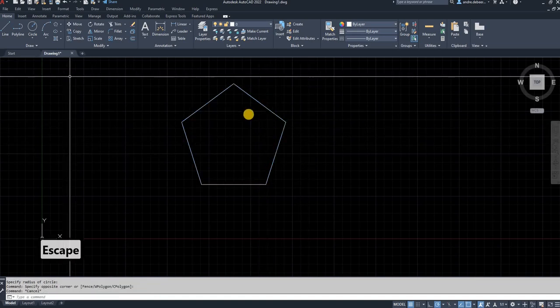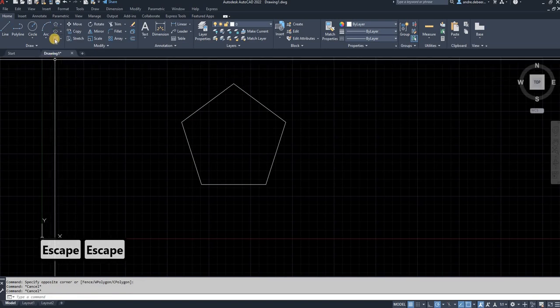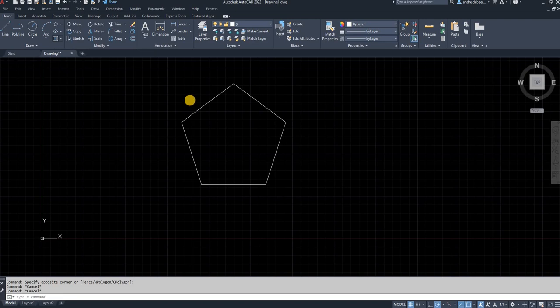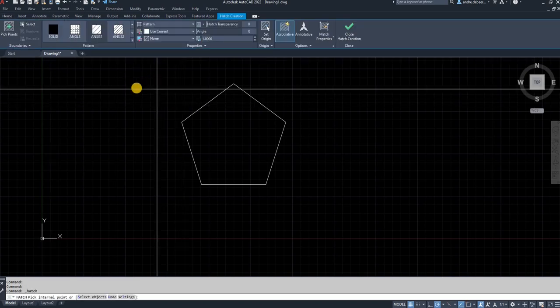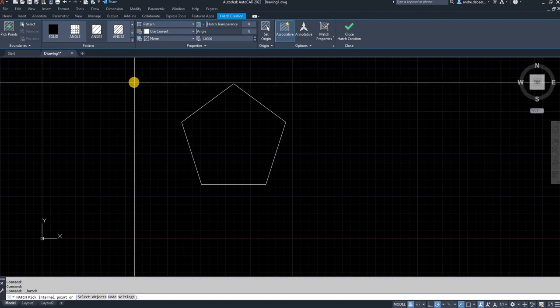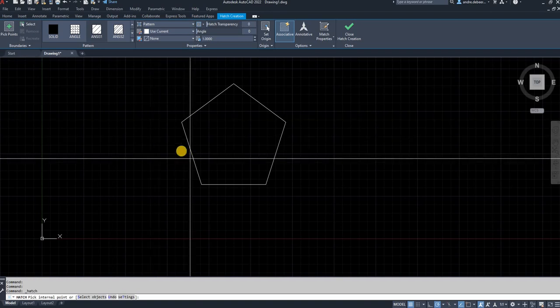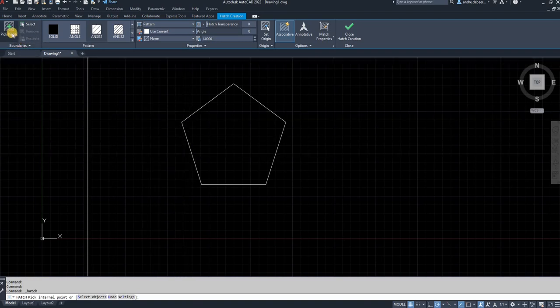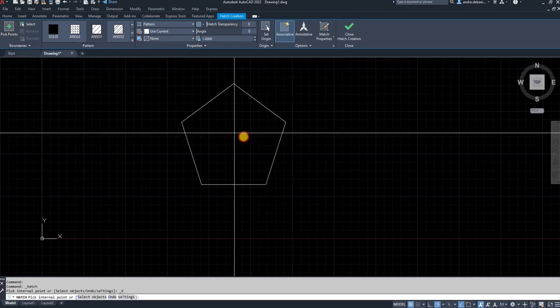So for my next command, I'm going to need an object in my drawing. I'm going to use the hatch command. The hatch command is just to fill whatever object you want, or alternatively, if you're drawing a house, to fill the walls, you're going to need the hatch command. The hatch command is very simple. You can click a point, or you can select edges or boundaries of an object. So for the first example, I'm going to click on pick a point,